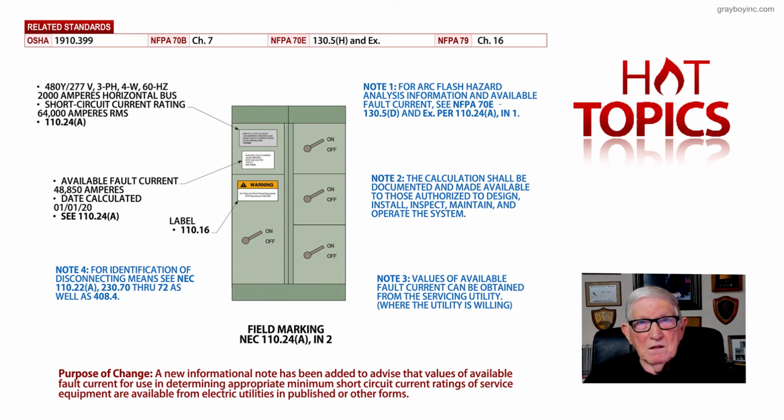And that can be an expense to determine that. It could be a whole room, or it could be just a certain distance in front of equipment. The arc flash boundary. And then at least one of the following: the incident energy, or the PPE worn in accordance with the job task that's being performed and using the tables of 70E that are listed in little (a) under 3.